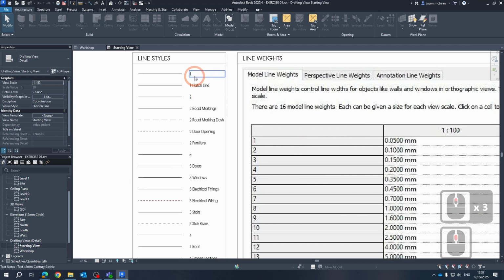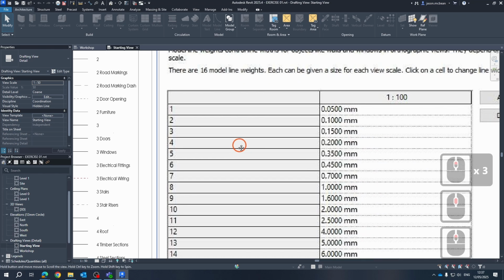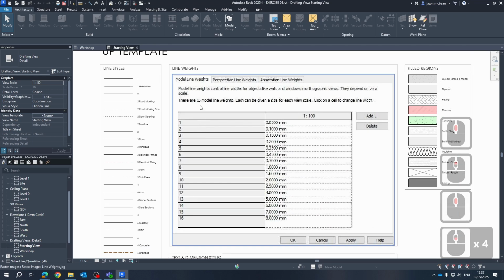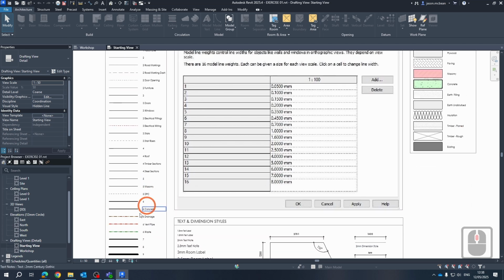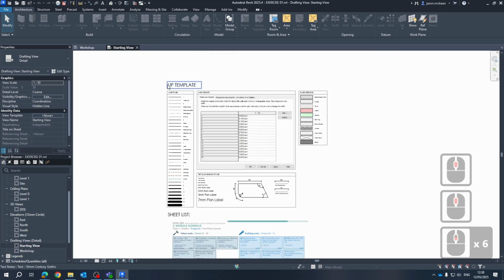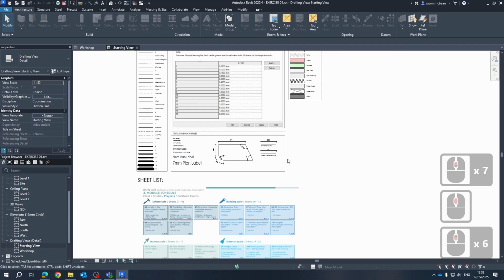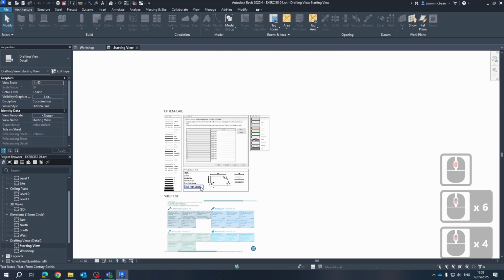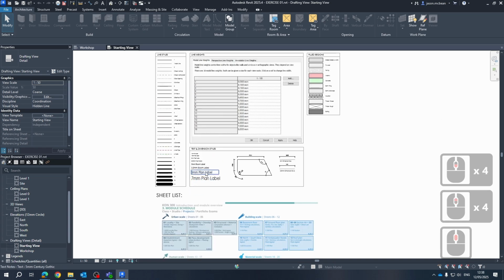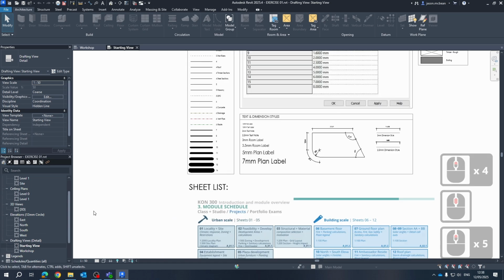That's why in Revit we always prefix the line work with the corresponding pen or line weight designation. This is just a quick way to know what I'm working on, and here's a quick guide to see how line weights work. Dimensions, everything's in here, font styles, text styles, all of this information is here ready to work with. There's a lot of information that you can ignore for the moment. This is focused for the 3rd years, but let's just get cracking.